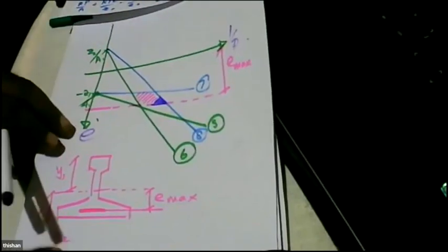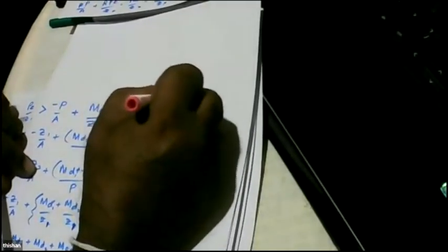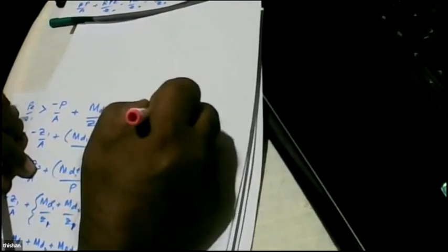And that's a huge advantage, because the moment you draw the Magnel diagram, you can find the pre-stress. And if you have used a loss ratio of about 30%, you can check the losses, but the chances are all those will be pretty okay.